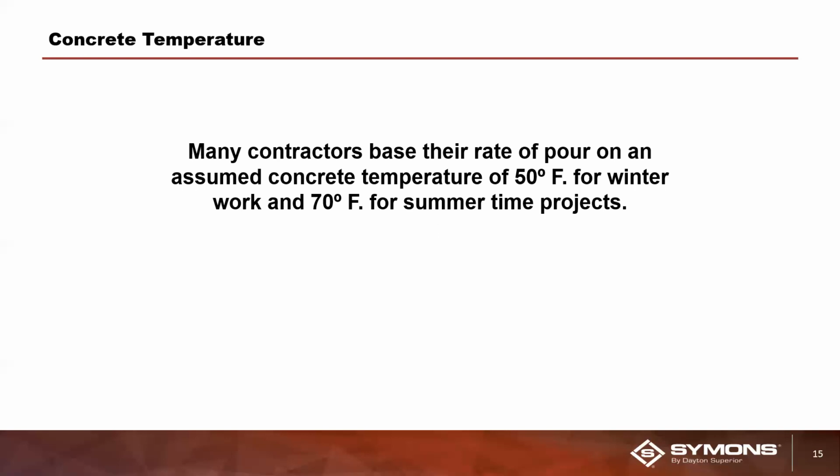And in the summertime, even if it's 75 or 80 degrees, the concrete is going to set up a little bit faster on you, which could be a separate problem all in itself. But typically, as far as form pressure goes, you will not be exerting the full maximum load of concrete pressure on that form.